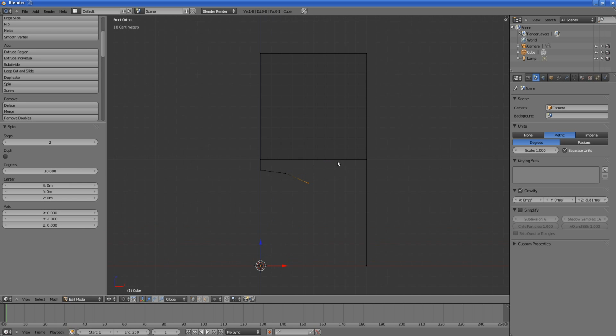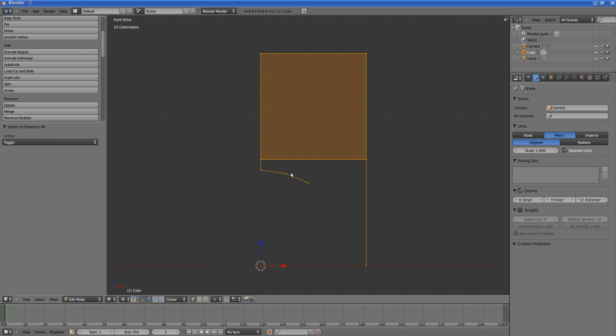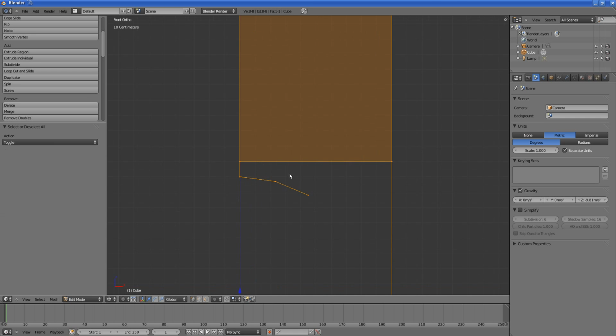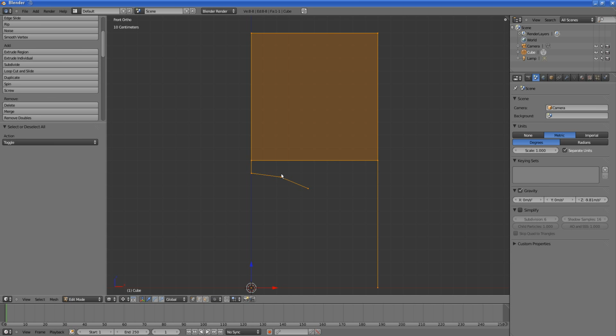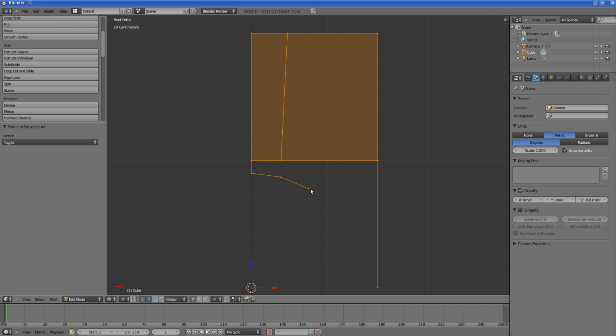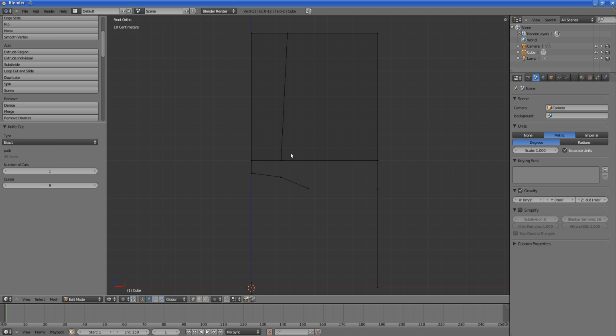So now I need to build a mesh. To build that mesh I need a proper topology. So I'll select all of these and then use the knife tool. Press the K key, move the mouse near this vertex and then make a cut. Similarly select all, K key, move the mouse near the vertex and make a cut. Cool. So we have this and this.